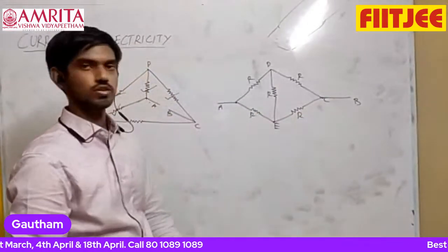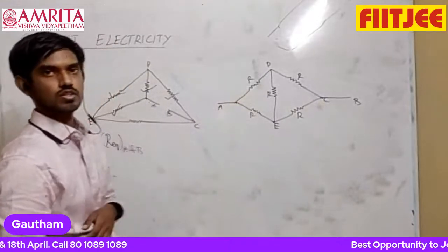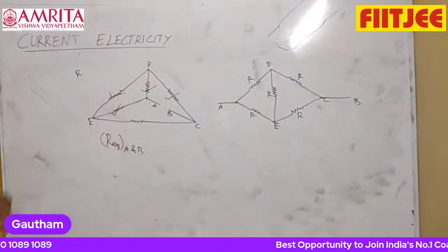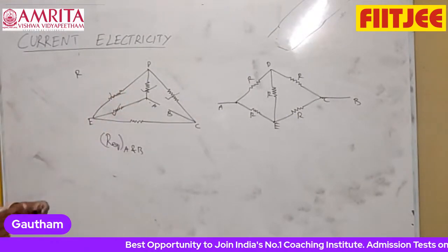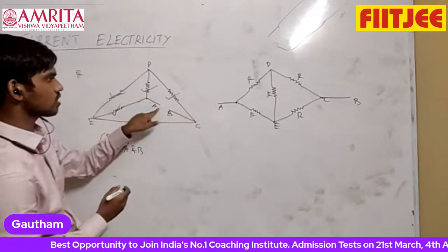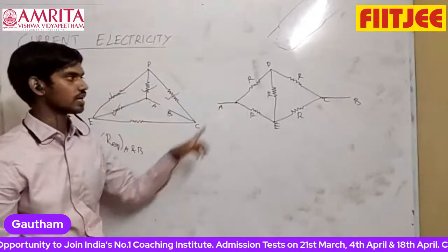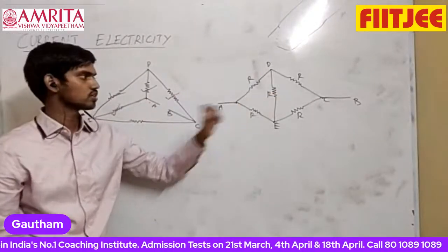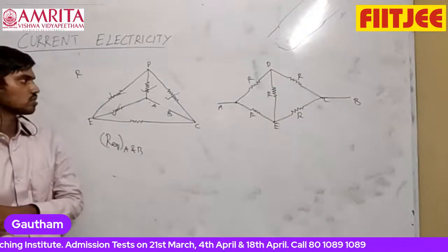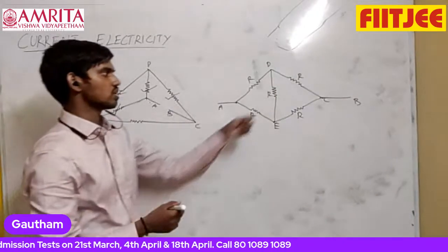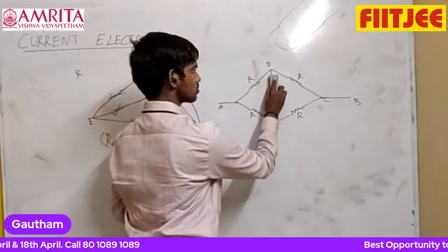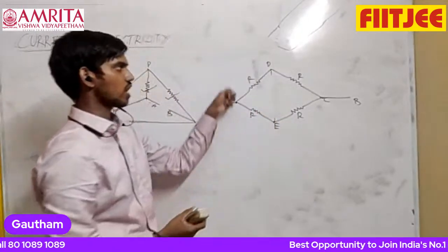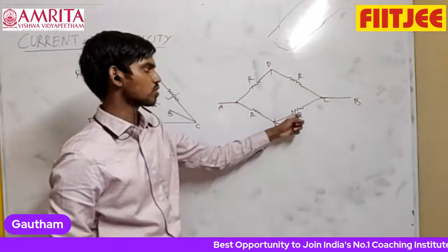Now, this is a very simple circuit, a straightforward Wheatstone bridge. Instead of giving the circuit directly, it might be given in some other form. You might have to imagine that, or the best way is to try to redraw in rectangle or diamond shape forms, so that it's clear that it's a Wheatstone bridge. So this resistance will not be playing any role. There is no current through this. So total resistance is R and R, 2R, R and R, 2R.